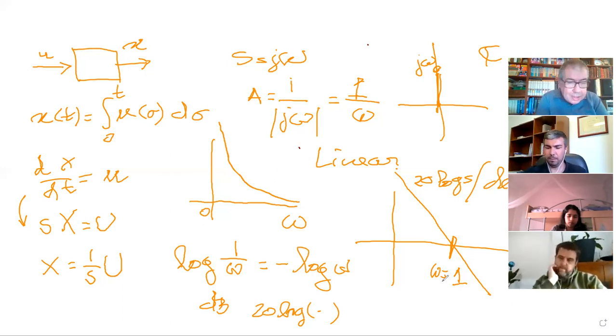And now we started relating dynamic systems, from linear differential equations to these so-called transfer functions, so that you can do computations in the frequency domain in the simplest way. We are going to explore this a little bit to see how we can design the controllers and study stability in a systematic way.